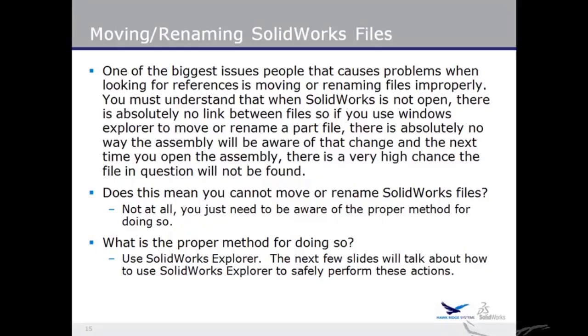The problem with that is that when you move files or you rename files, it can't rewrite those references. So when you go to open the assembly or the drawing again and files have been renamed, well, it can't find those files because it didn't know they were renamed in the first place.